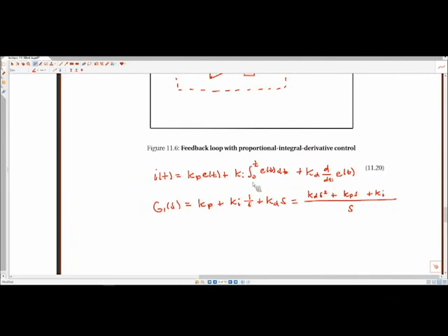So all the units are different, and when we talk about gain values, it has to be within that context. It's a little bit dangerous to talk about magnitudes, but as long as you keep consistent units, it's a general rule of thumb that the integral gain is about 50% to 100% of the proportional gain. Okay, I've gone over. We'll show this thing on Wednesday then, first thing.